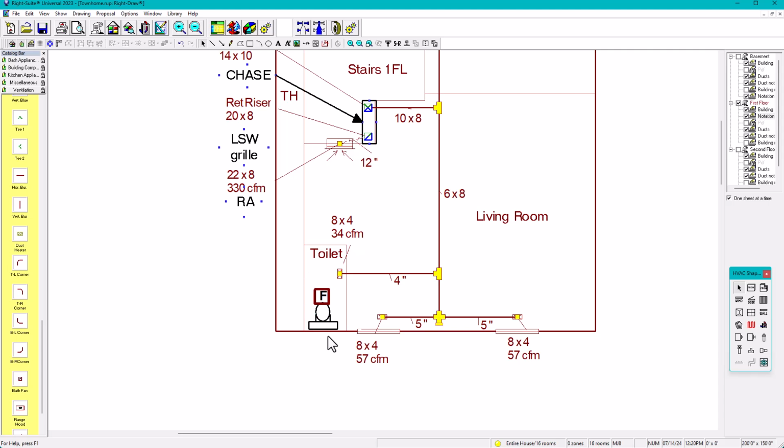Okay, and then we're going to put a duct because this is the exhaust fan and the exhaust fan has to have a duct, right? So let's put the ductwork, and you have two options. You can always exhaust it through the roof or to the sidewall.